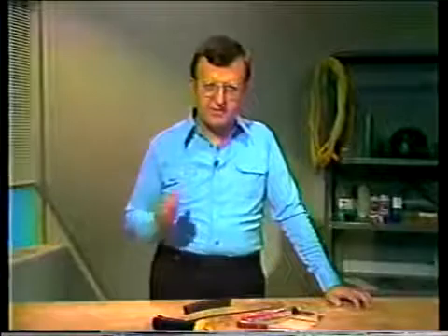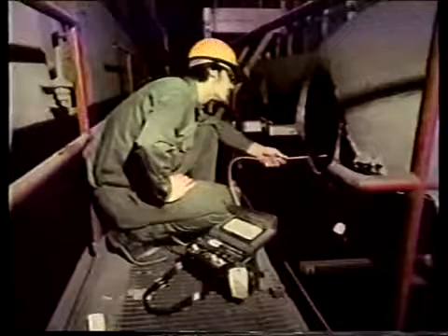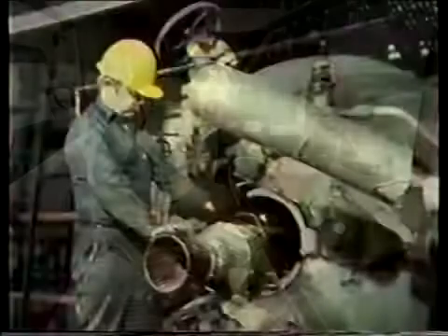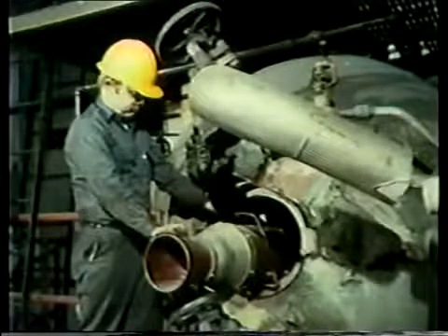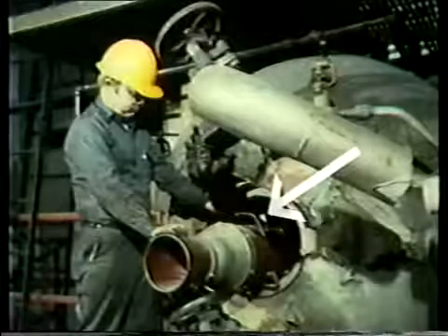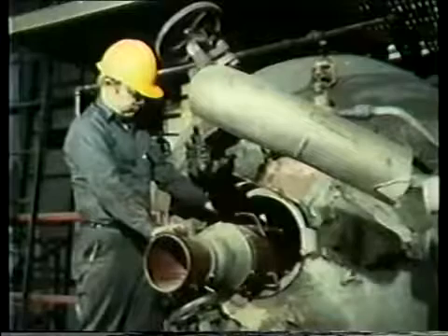Whenever you check for these problems on the water side, remember that safety is an important part of your inspection. Before you go inside a drum or moisture separator, make sure that there's adequate ventilation. The air should be tested to make sure that there's enough oxygen and to see if there are any poisonous or explosive gases present. If there isn't a noticeable draft through the manways, you should set up a blower. If you can't get good ventilation, or if harmful gas is present, do not enter that boiler.